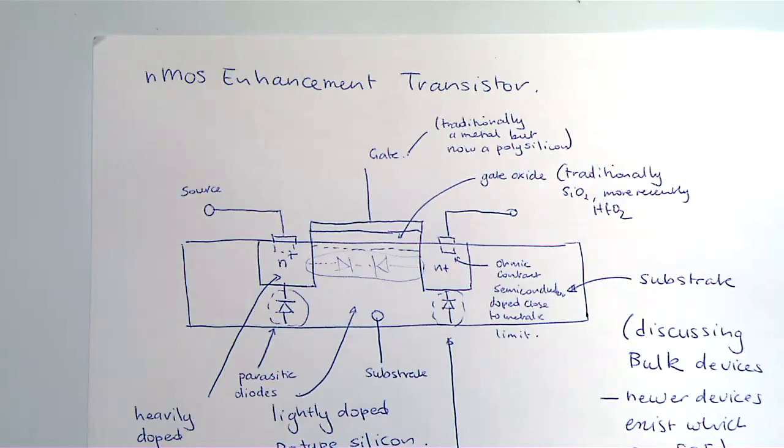And these days, they can make these cylinders 12 inches in diameter, right? When somebody says to you, we've got 12-inch wafers, essentially what they're talking about is when they've got this large crystal, they cut these wafers across, and then you've got something like a dinner plate, which is 12 inches in diameter, right?